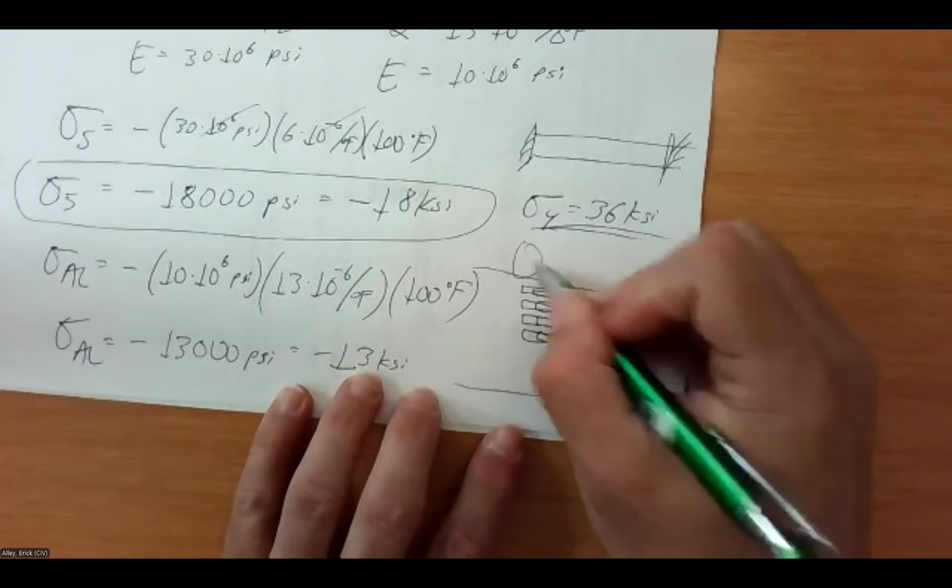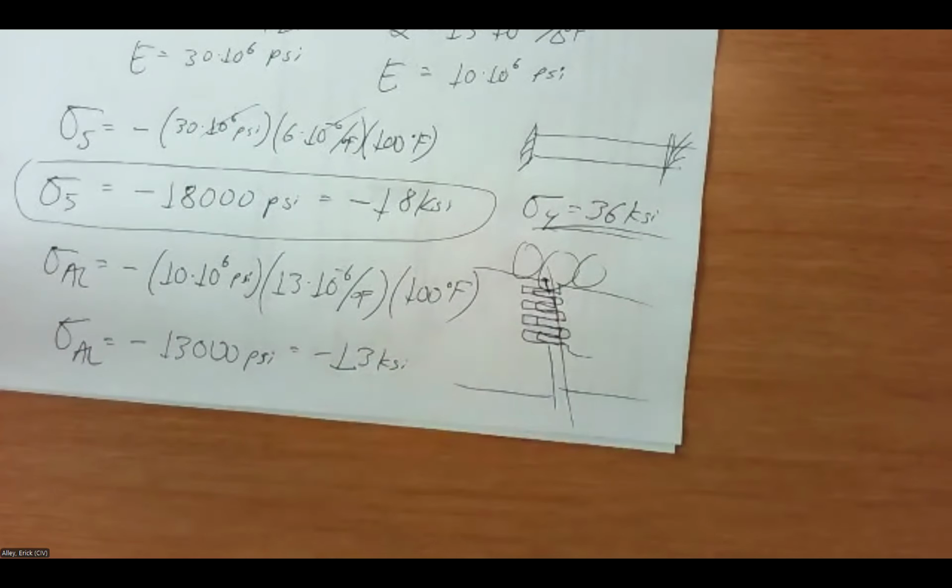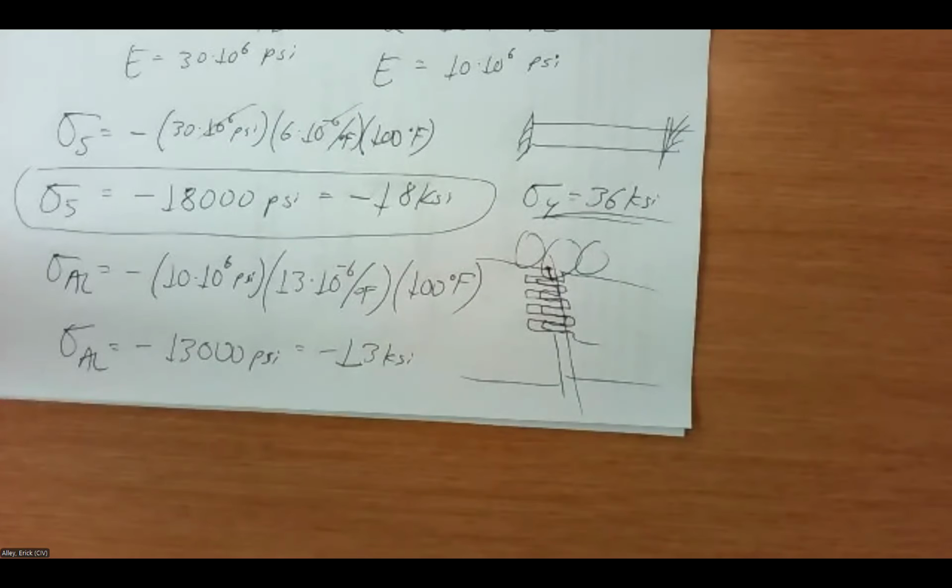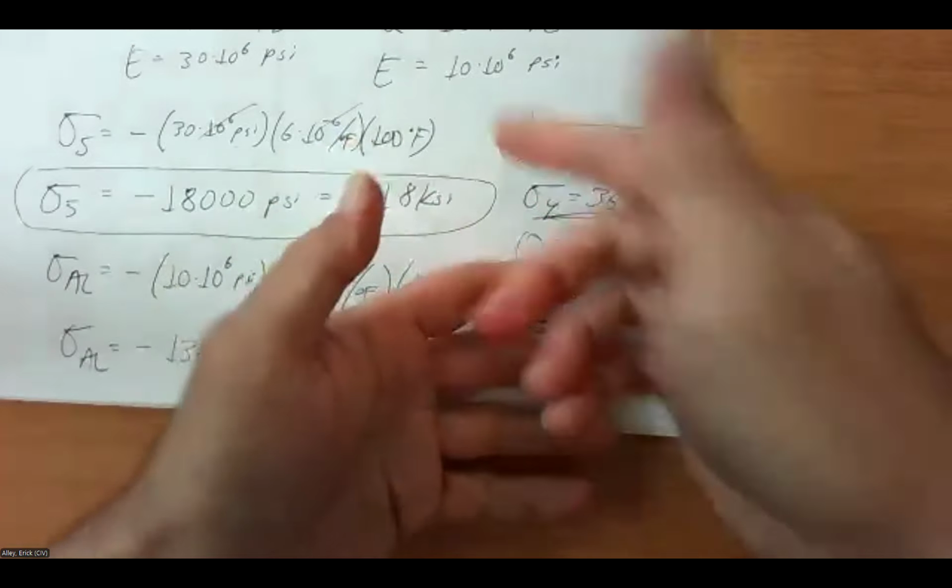So as we're driving over it and our tire rolls over, we go from one section of bridge to the next, it's thump, thump, thump. If we drive over that bridge in the summertime and all these expansions happen, then the little grooves here will close up. That little gap will go down, and we'll hear a really soft thumping in the summertime as we drive over. If we drive over that same bridge in the wintertime, the opposite thing happens.